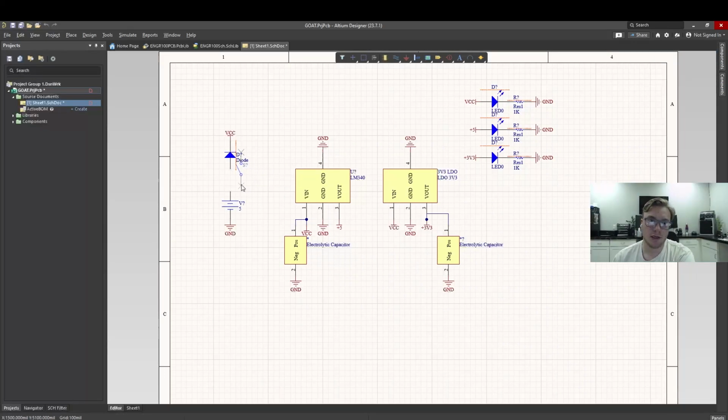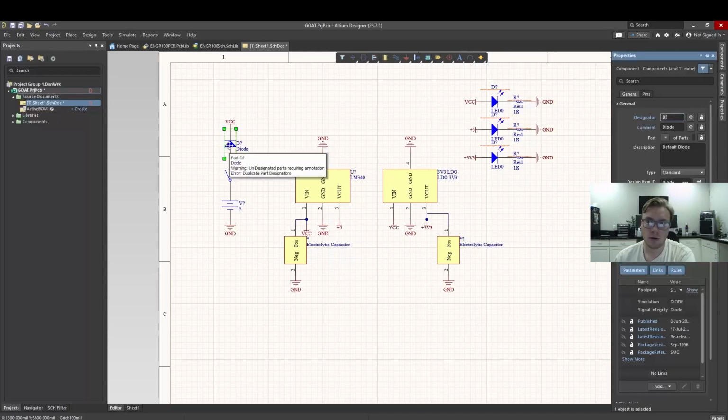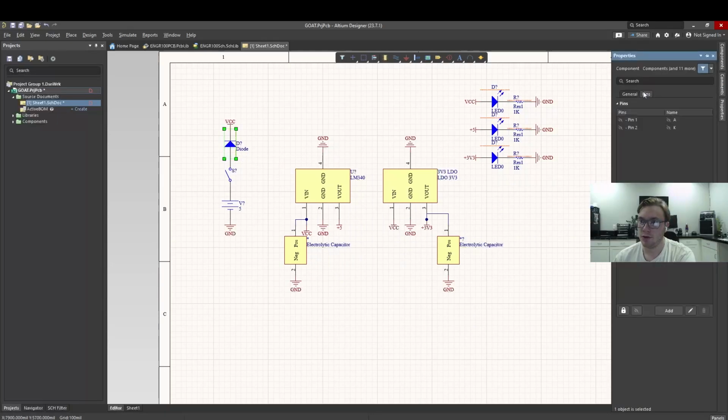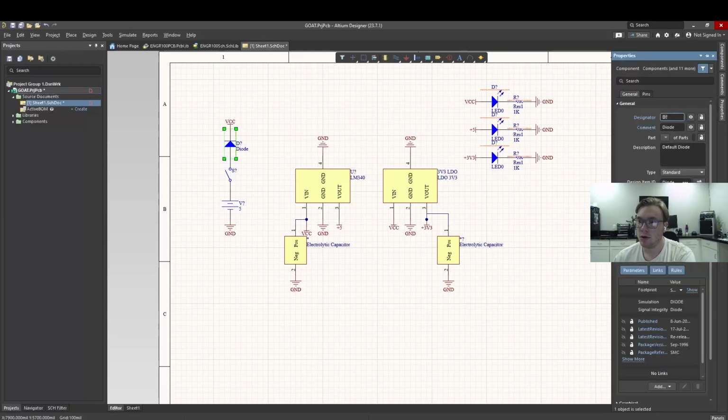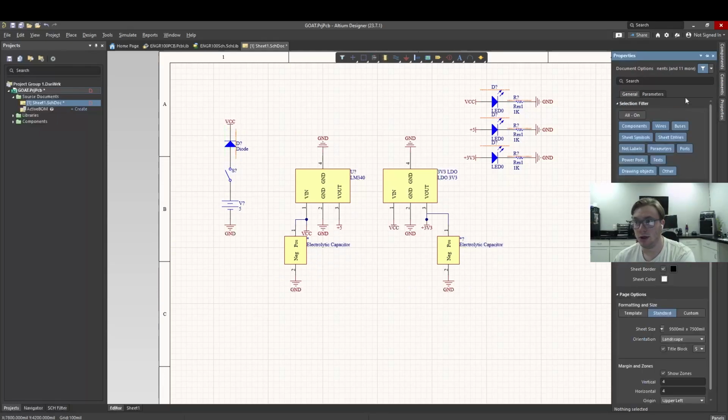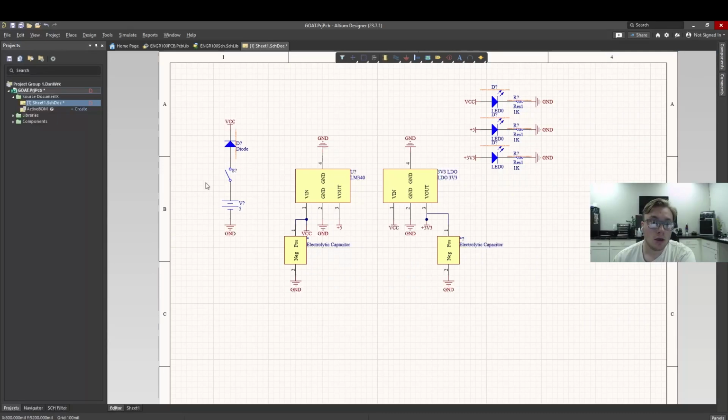So then we're going to run this. We're going to put that right there. Select this diode and this net and move those up. Are those connected? We can check by going to pins. Everything looks good to me. So now we've got our switch in place.